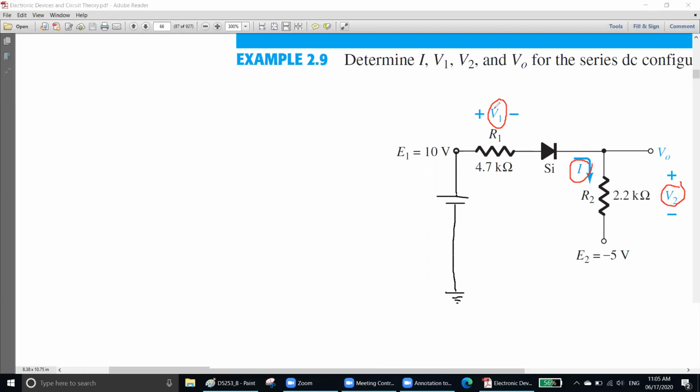Here you have another battery that is minus 5, right? Minus 5 is actually a difficult one. Let's redraw the circuit by using another battery. We will give a 5 volt battery and the minus will be connected because it was minus 5, and the plus point will be going to the ground. Understood? Plus 10 means plus is connected, minus is ground. Minus 5 means minus is connected, plus is going to the ground.